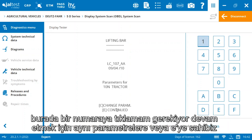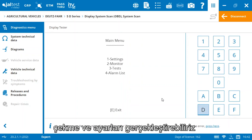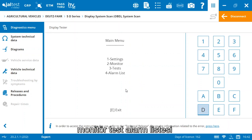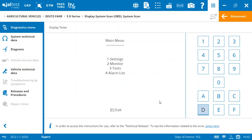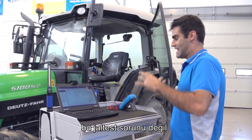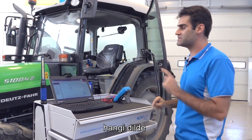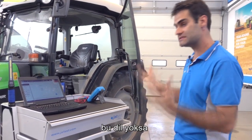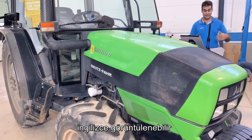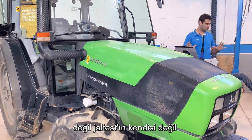Here we've got the same parameters, E to continue. I want to continue, and here we've got the main menu for this rear lift, for the hitch, and we can perform settings, monitor, test, alarm, list. Also, if we find different languages here, it's not a problem of Jaltest. Jaltest tells the electronic control unit in which language it should be displayed. But if the electronic control unit hasn't got this language, it can be displayed in English or Italian, and it's a matter of the electronic control unit, not Jaltest itself.